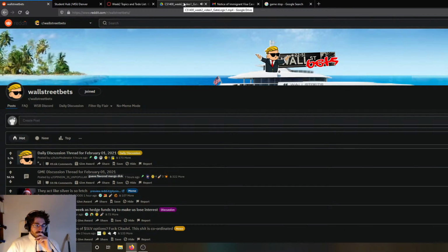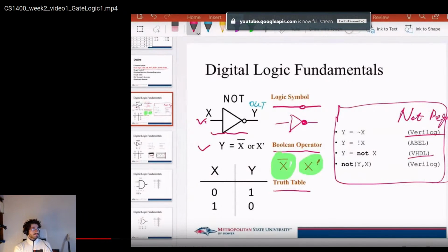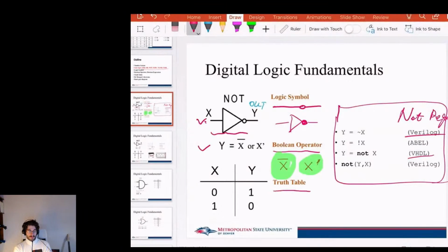So the last thing here is called the truth table. The truth table is actually a small chart to list the input and output logic relationships. Usually we list the input signals on the left-hand side and separate the inputs and the output by a vertical line. The last column on the right-hand side is always called the output variable.